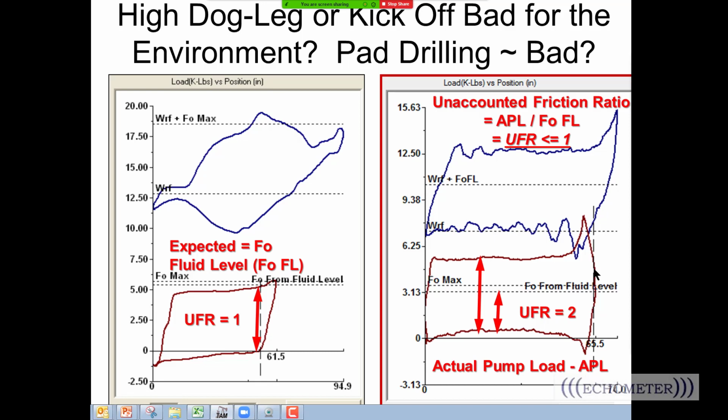Inside TWM and inside TAM, there's a reset button that defaults the damping factor. And what we've found over 30 years of experience is that you can estimate the damping factor based on the well depth and be reasonably accurate when there's not a viscous crude in the well. And so normally when you don't have high viscosity fluids, then the damping factor, just by going into the TAM